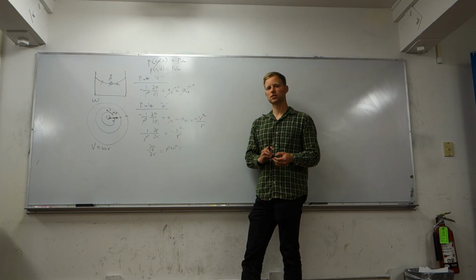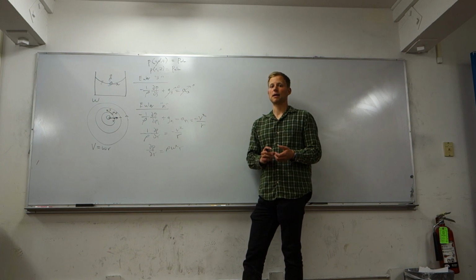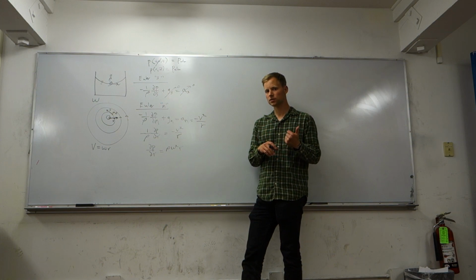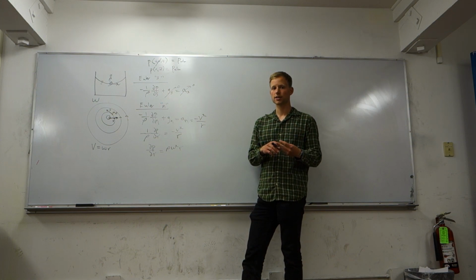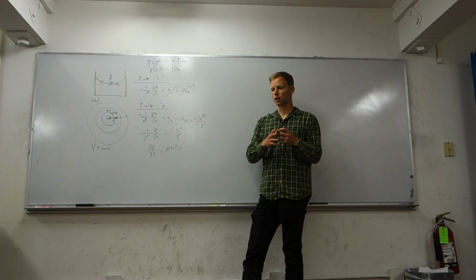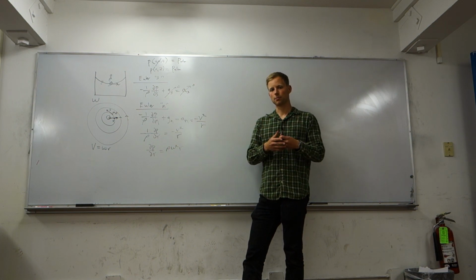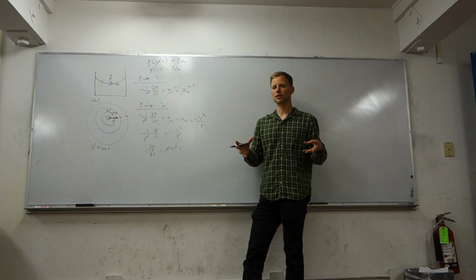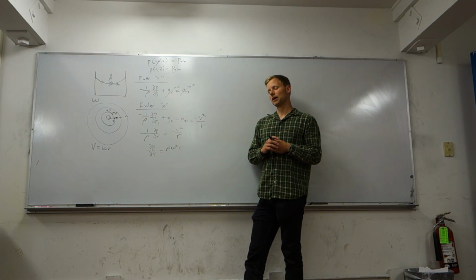So Navier-Stokes is derived by doing momentum balance on a differential fluid element, allowing for viscous forces, pressure forces, and acceleration. And it's a big, long equation in one dimension, and if you want to write equations for three-dimensional flows, you need 3 of them. So you have 3 equations, each of them has a number of terms, and they're all partial differentials, nonlinear, second order, so they become difficult to solve.